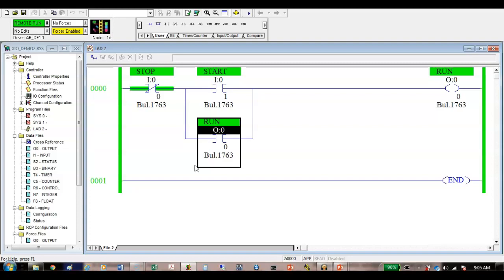See that? So I'm going to start this thing up, and all of a sudden something happens, and I can stop it with this normally open push button. I can start it, I can stop it, I can start it, I can stop it. Okay, but I'm going to start it, and then this wire right here breaks. And now I'm hitting the stop button. What's the problem? I can't stop it. And wires break all the time. So here I've got this 200 horsepower motor that's out there running, and I'm hitting the stop button, and it won't stop. So what we'll do is we'll go offline.